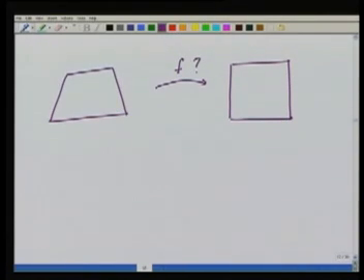So the mapping, you see that this is a domain with straight edges, going to a domain with straight edges. So here for the mapping of the geometry, in this case, as long as I do not have curved elements, we are going to use bilinear.